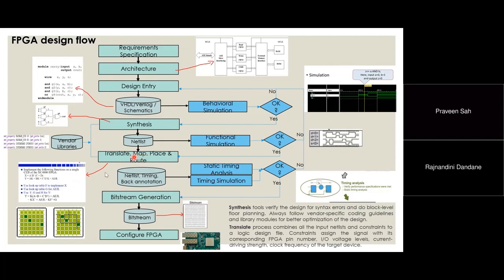Now map is nothing but, you see, you want to use these logic blocks. You decide that, which means you are mapping now. There are different logic blocks, but you can configure which to use, based on whatever simulations you have done, the timing, the delays, considering all these blocks I am using. This is nothing but map.